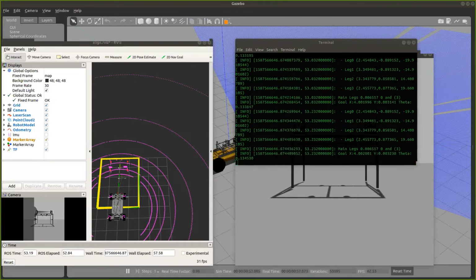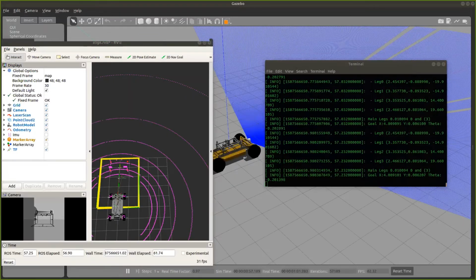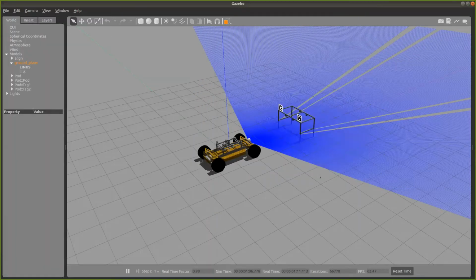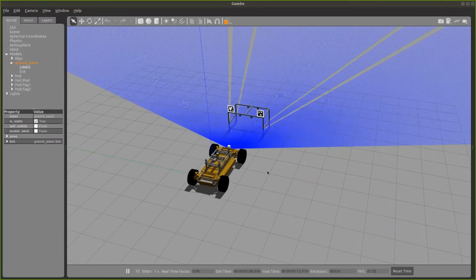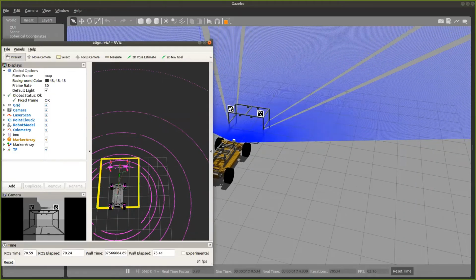And then we've generated a set of waypoints for approach navigation. Those are visible in RViz as the green arrows shown in the figure. And then the execution of this approach navigation will be done with pure pursuit and PD velocity control. And then we'll see that the chassis will follow these waypoints and align itself under the pod.